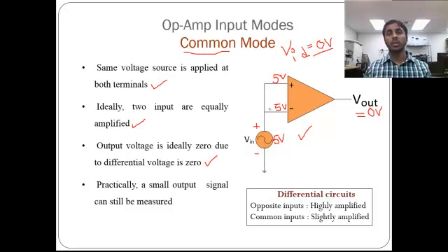Maybe because of temperature changes, maybe because of the change in the barrier potential of these transistors, which we call VBE, which we assume is 0.7 volts. Because of that voltage, there is always some current. If there is a voltage, there is a movement of electrons, and if there is a movement, there is a current. So even though there is no input signal, internally there may be a current and a very small error voltage.